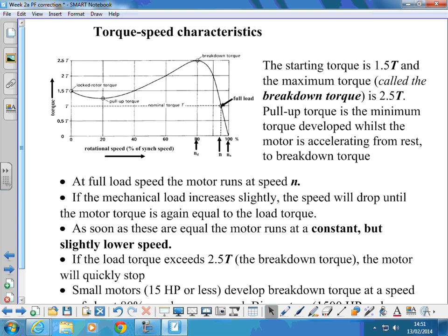The other thing they do is, in a real motor, the bars in the squirrel cage are quite often skewed as well. They're not straight. I've read some information, not in detail, saying it quietens the motor down. I don't know why, I didn't read the detail.